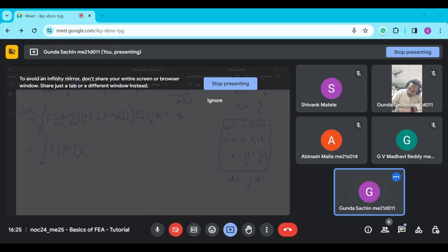So we can write 0 to 1, E times 1 by 4 times 2 plus zeta by L, minus 1 by L times minus 1 by L, which is nothing but minus times minus, plus 1 by L squared d zeta, and then there's 1 by L here, L cubed, u1 plus 0 to 1, similarly E times 1 by 4 times 2 plus zeta by L times minus 1 by L cubed d zeta u2 is equal to q1.